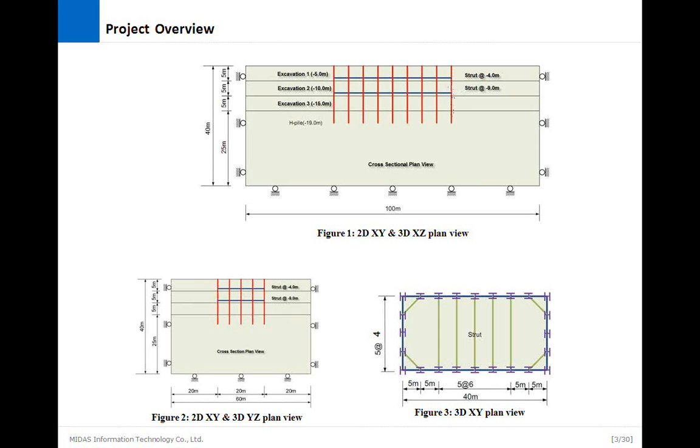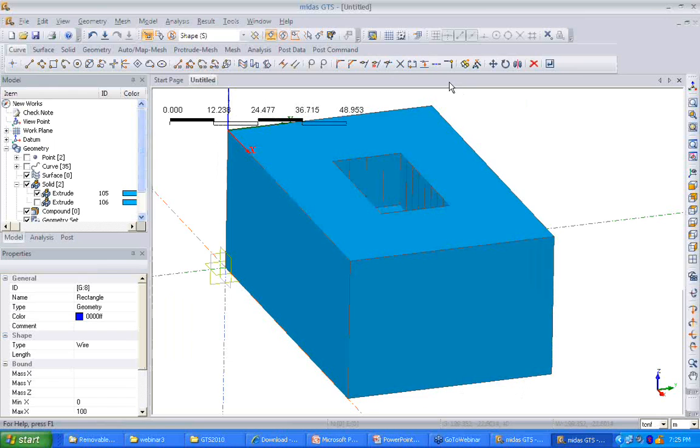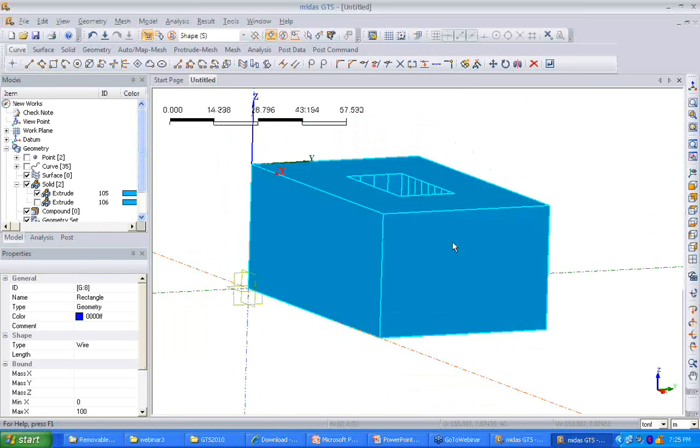The motive why I'm dividing the whole excavation solid into 5 layers will be reflected in the coming demonstration, because this is a so-called cheat code which I'll be using to model my wales, as well as ensuring nodal connectivities between the piles at the later stage where we'll be meshing. So going back to the model again.